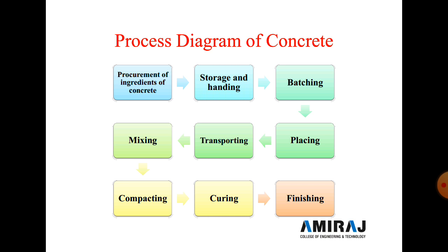Generally if the site is a larger site, an RMC plant is prepared near the site or on site, and then the material is transported by pump, and then mixing. For proper mixing, a batch mixer machine is required. If the work is larger, a mixer machine is required, and if the work is small, hand mixing is done to prepare the concrete.